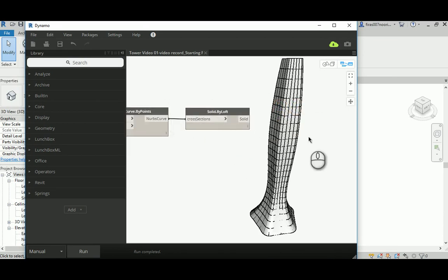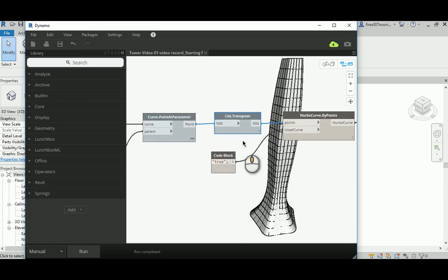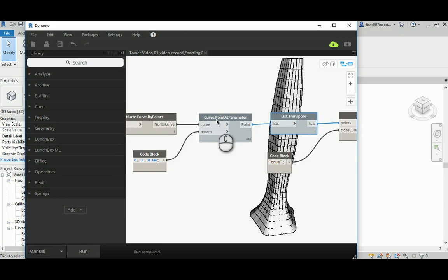That's the result. The whole model here is just a process to make a form, which is a very basic level in dealing with Dynamo to create a simple geometry. Even the horizontal and vertical divisions, I used an extra layer of divider, like a curve, by using this node Curve.Points, in order to divide that into groups of sub points, and then we generate lines, or NURBS, based on that. That's the tier of modeling in Dynamo, or in parametric modeling. We can call it form modeling.